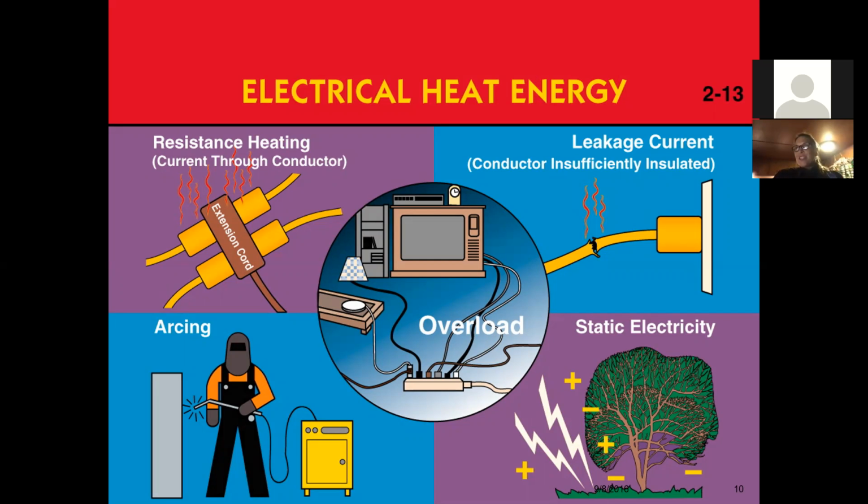Extension cords are not meant as permanent wiring options. You should have those installed by an electrician as a permanent source of electricity, not leave an extension cord as the permanent source. That's a temporary use that can be watched, to make sure we don't get the damage that's shown in that top right corner.